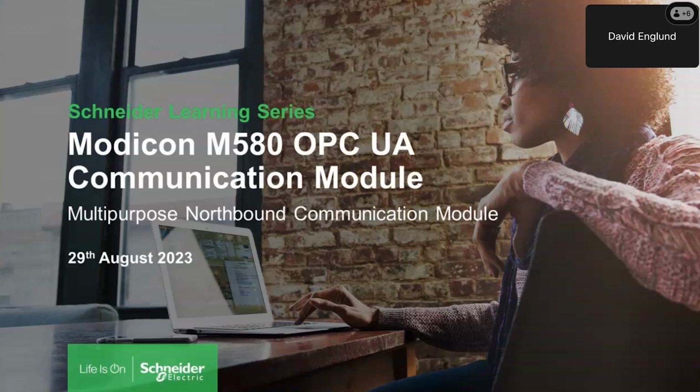Right. And Lou, this is Robert. That is correct. We've done that where the integrator would have to have credentials assigned to the M580 in order to make the secure connection. In an unsecure connection, all they would need is the OPC UA IP address and the port number to get into it for programming with EcoStruxure Control Expert. Once you make the connection, of course, if the client has established any application passwords, then you would need those to get in.